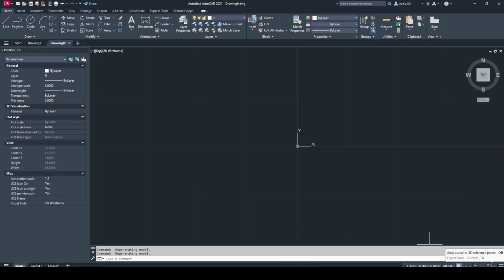The most commonly used of these is 2D Object Snap. When it is toggled on by clicking on it in the status bar or hitting F3, it allows you to snap to a specific part of other drawing objects. To select the snap mode, you click on the arrow and select the options from the menu.